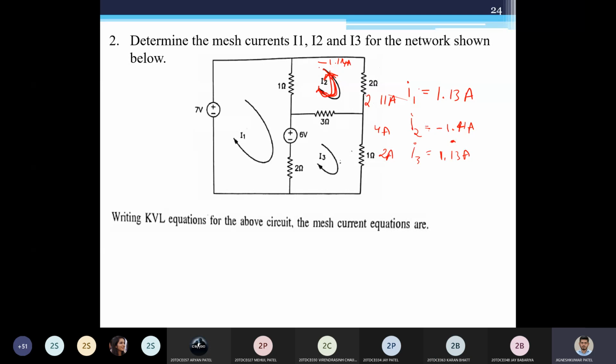So actually the current is flowing in anti-clockwise direction like this, but for the calculation we did not know this earlier, so we took an assumption and calculated the answer based on it, and that's why the answer is negative. So negative answers are possible. It is not wrong at all. The negative just represents a current in the reverse direction compared to your assumed direction of the current.